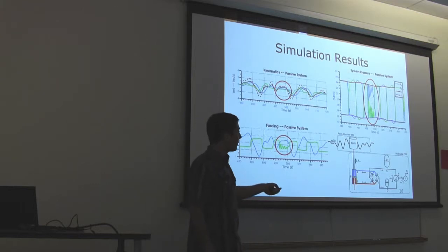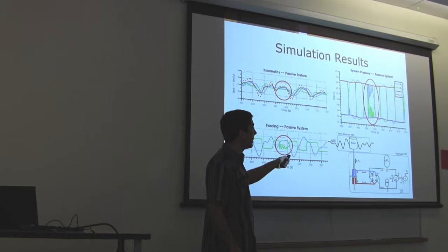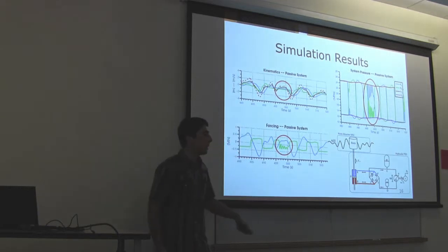In order for fluid to flow to the high pressure side, it needs to overcome the pressure in line C. We can see here that it's not able to do that, so fluid gets trapped on this side A and B here. And because it's modeled as slightly compressible, it has this spring-like effect where we have this high-frequency oscillation until it dies out, until there's enough excitation force for it to open that check valve.